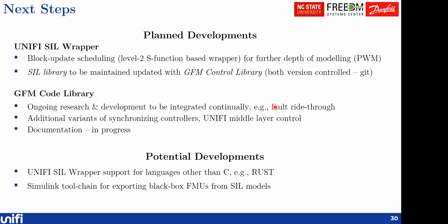And the last thing that I talked about is how we can take the SIL modules with the control software and the power stage and create an FMU block so that we can take it from MATLAB environment and integrate it in PSCAD or some other simulation environment where you can basically simulate very large power systems. That is something we can explore for sure.